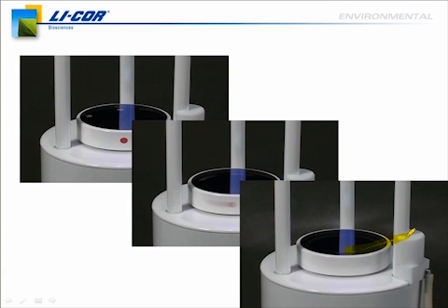We're spinning and cleaning this mirror for a period of, like I said earlier, maybe 20 or 30 seconds, and then the pump shuts off. The mirror continues to spin until it's dried itself off, and then it comes to rest, and you continue making measurements. So this is a fully automated system that allows you to keep the instrument running in the field for longer periods of time. And again, you can set this up so that it only checks and washes between 30-minute averages if you want.